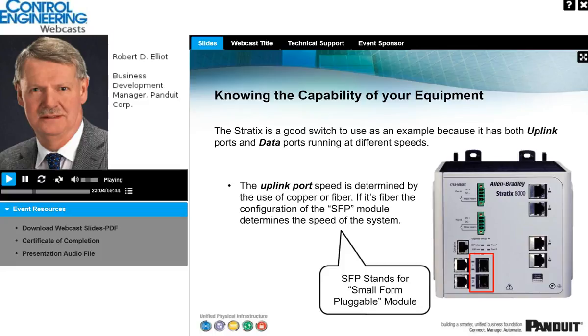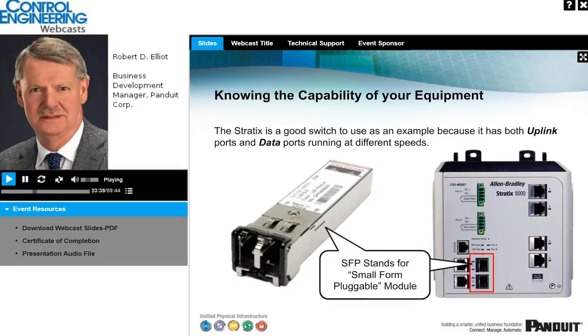Let's just look at that in a bit more detail. The SFP modules will go into those 2 ports. There are 2 ports there. It really depends how you use it, but if you use it in a hierarchical star arrangement, one of those ports would be a main port, and then the other would be a redundant port. If you used the switch in resilient Ethernet protocol, for example, then effectively one of those ports would be used for going round the ring clockwise, the other one would be for going round the ring anti-clockwise, for example.